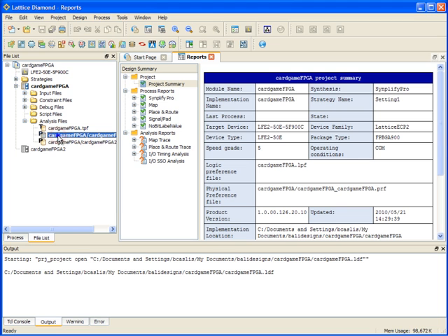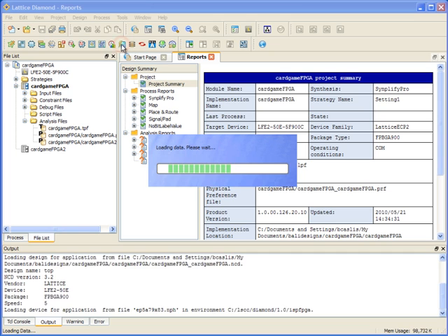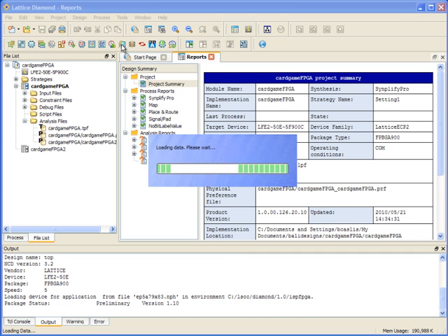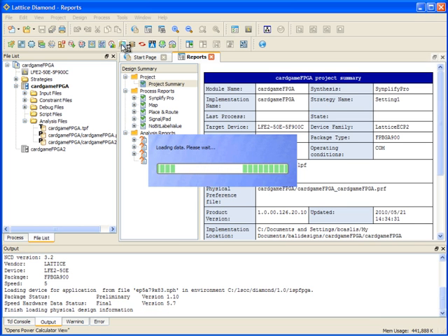So let's go over what happens with these with Power Calculator. First, I'll set them all inactive. If they're all inactive, and I go to the Tool menu and launch Power Calculator, what happens is Power Calculator opens and it loads information from the common design data that's in memory for the design that you've implemented and reads that, parses it, and does power calculation on it. So it's reading the data from your active design when you run it without any PCF file being active.